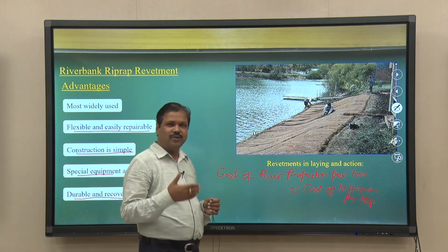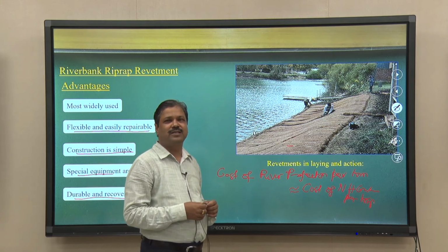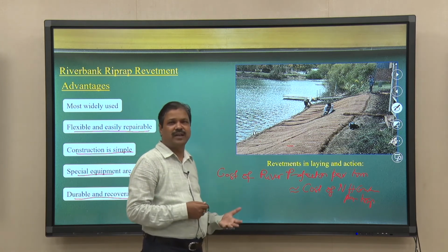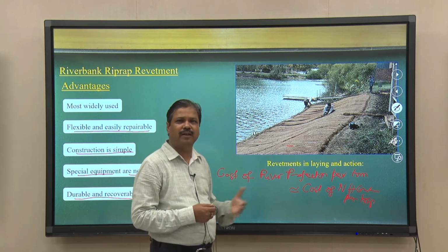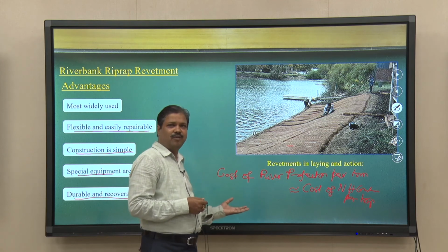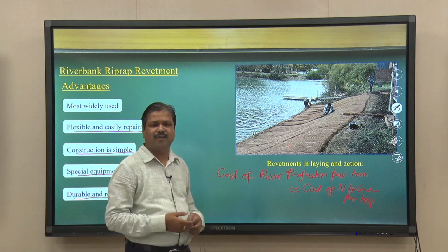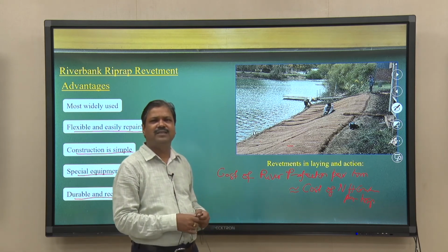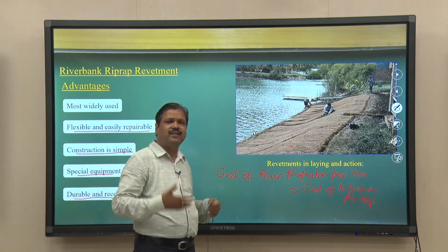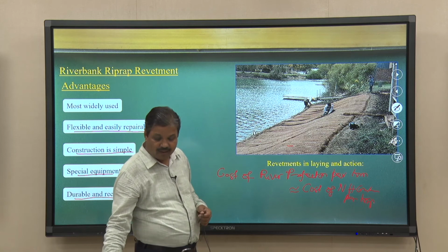That is not the case, because the US Army Corps of Engineers have done very significant studies and have remarkable success stories in rivers in the USA, particularly the Mississippi River. So, we should take knowledge from them. As river engineers, it is not just about dumping stones on the river bank, because it is very expensive work, since the cost of river protection per kilometer is as close to the cost of national highway construction per kilometer. That is the reason we should take the knowledge from the US Army Corps of Engineers, and both those success stories and the local knowledge we should build in to make a successful story for river bank protection or river stabilization.